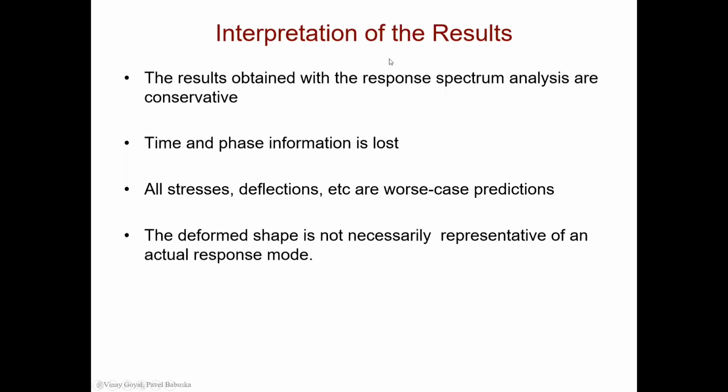You're going to use the results, and it's important to understand that the results are conservative. The time and phase information has been lost, of course, because the SRS was developed based on a time domain input. Remember, the SRS was developed based on the maximum acceleration caused by an oscillator that was tuned at a particular frequency. All stresses and deflections tend to be the worst case predictions, and the deformed shape is not necessarily representative of the actual response.